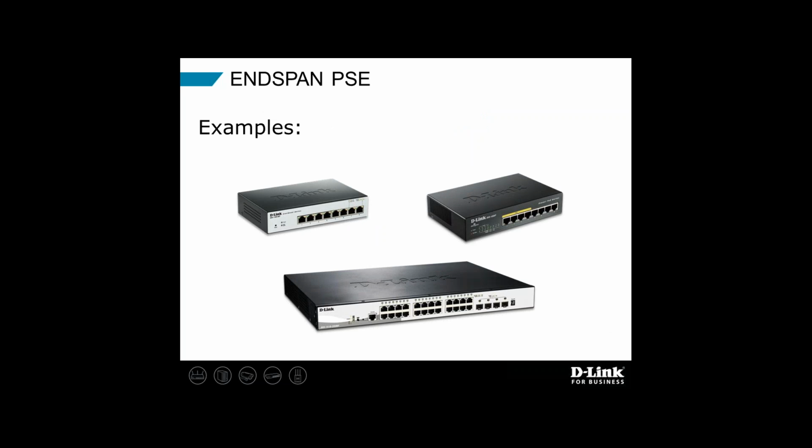These are PoE switches. There's a couple 8 ports, there's a 24 port. These are Endspan devices because they generate the Ethernet signal as well as act as a PSE by putting the power on the cable.